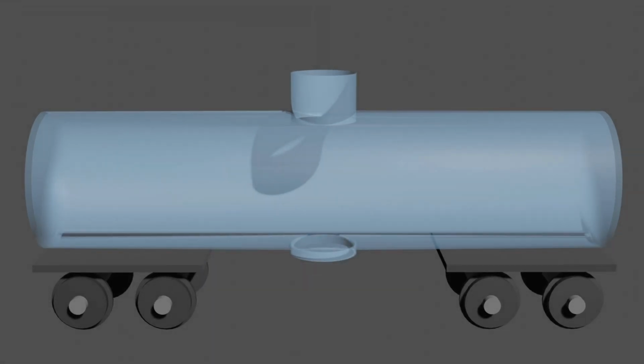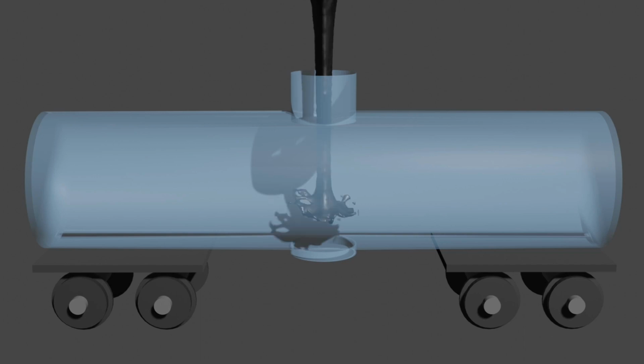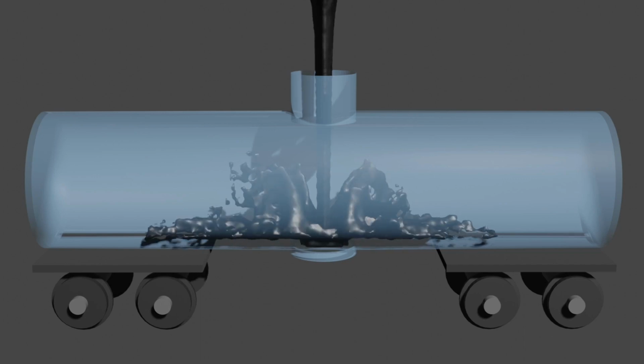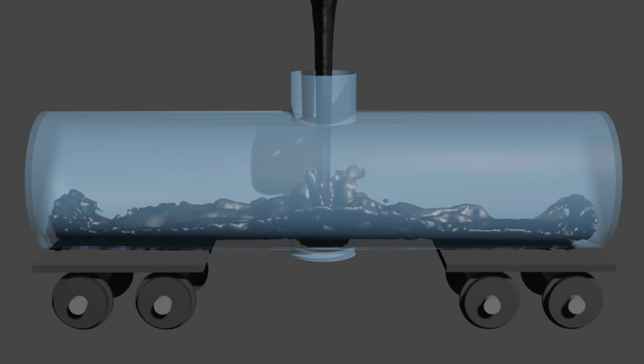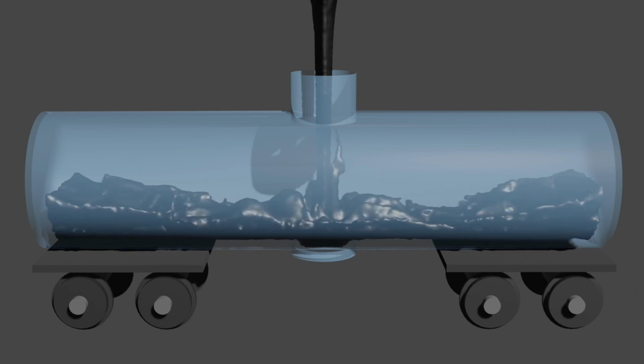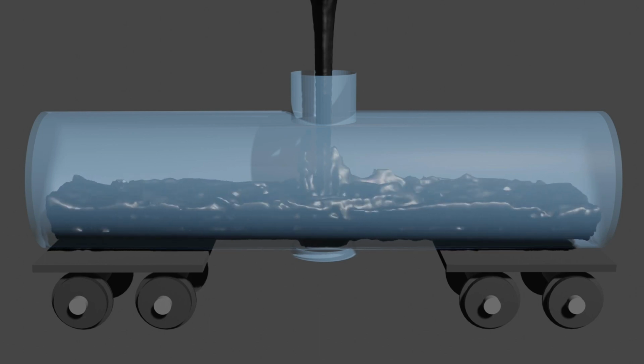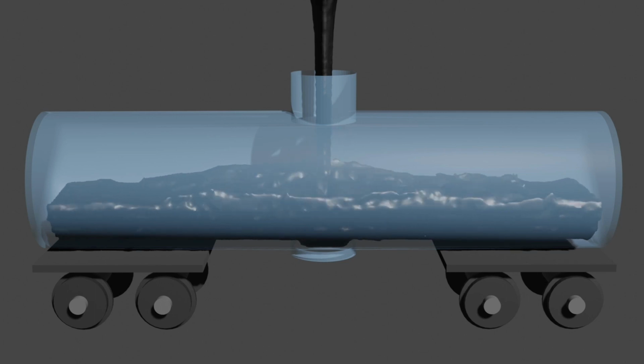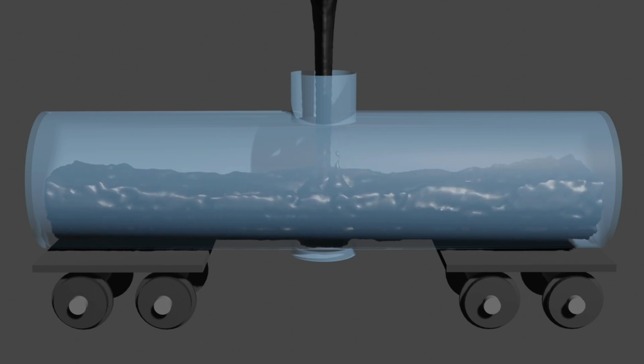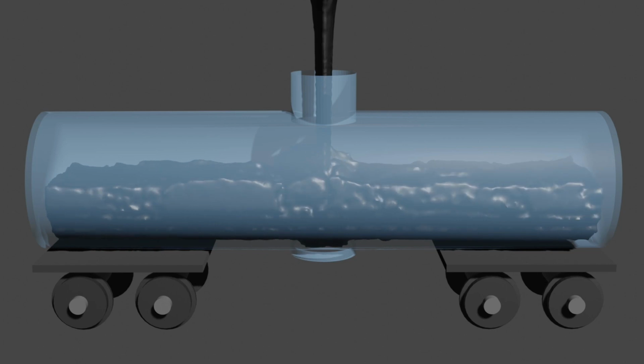This second example shows the same railcar, however the crude is loaded first and then the scavenger is added after. Since the car was already loaded and there's limited turbulence or agitation in the car at this point, it is likely that the scavenger and crude contact is poor. In this case, there's also a good chance the product will still have high H2S when tested.